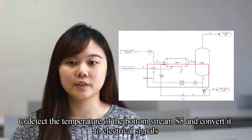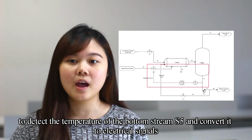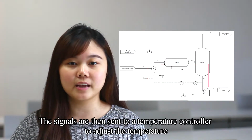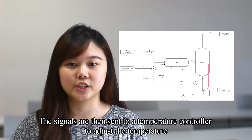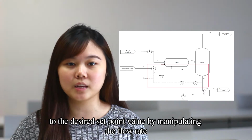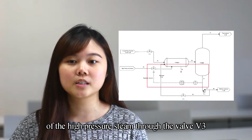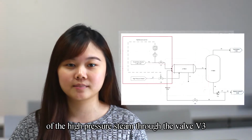The original control system for this process is a feedback control, where a temperature transmitter is used to detect the temperature of the bottom stream S5 and convert it to electrical signals. The signals are then sent to a temperature controller to adjust the temperature to the desired set point value by manipulating the flow rate of the high pressure steam through the valve V3.